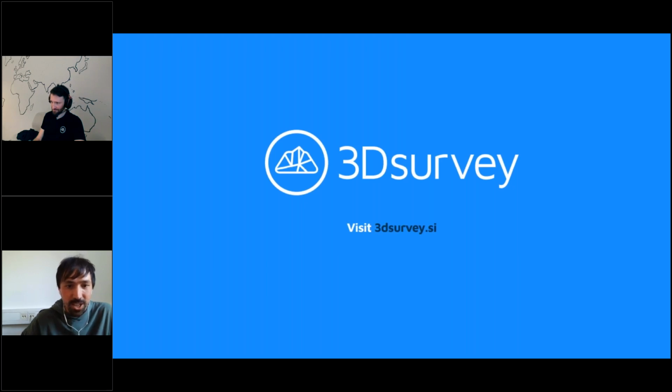Then the second question from Patrick: is there a possibility to draw a profile with a 3D mesh? Because I think this is possible only in point cloud. Patrick, you're right. The profile lines are calculated from point cloud points, but there is one trick which was not in this session, and this trick is how you can convert mesh into point cloud. It's nothing hard.